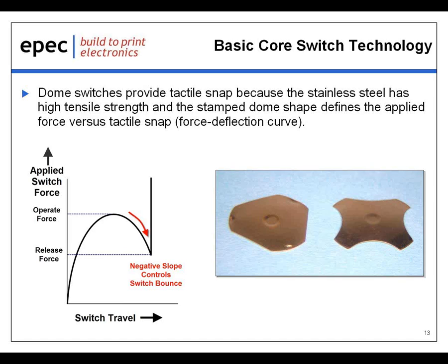On the graph, notice that the V-shaped notch at the point where the dome switch meets the printed circuit board actually controls the contact bounce. If the notch is very sharp, the contact bounce will be minimized. However, if this notch looks more like the bottom of a letter U, the contact bounce can be very long. Engineers call this V-shaped notch a stable servo point, where the slight change of applied force will not change the position of the dome or cause any intermittence. This feature is the reason that the switch has snap feel and is different from being just a linear spring.